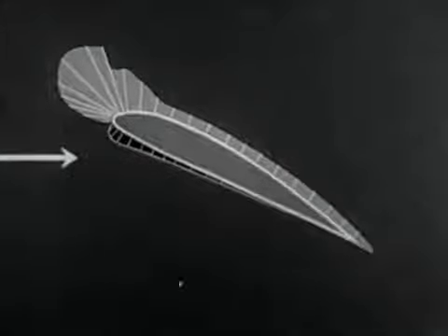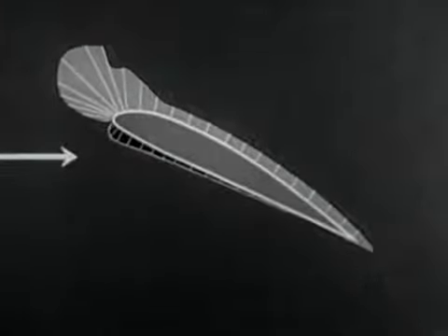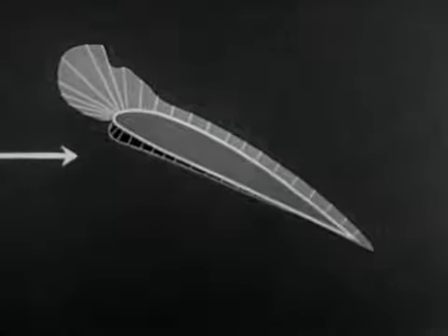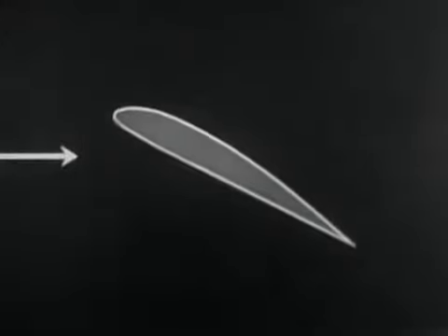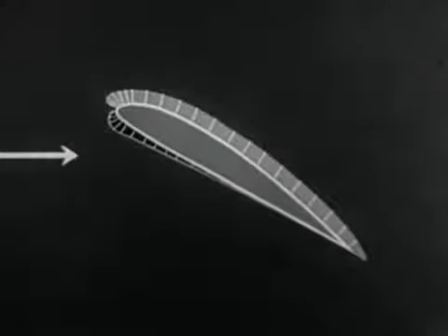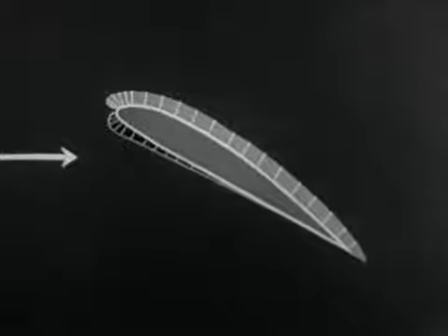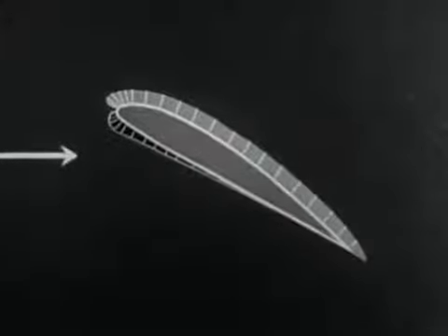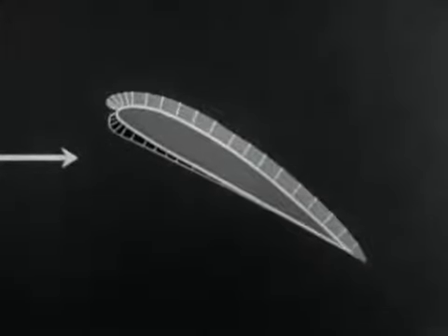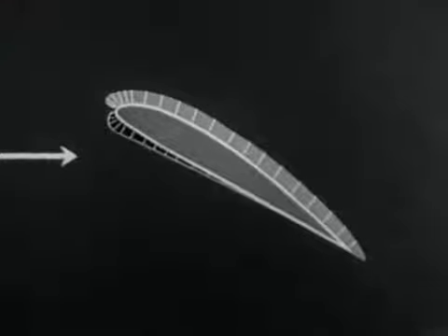Increased angle of attack brings no important change in positive pressure value or distribution, but the negative pressure area is tending to equalize in value over the entire upper surface of the wing. At this angle of attack, the forward protuberance disappears completely, and an area of nearly equal negative pressure blankets the entire upper surface of the wing. Positive pressure areas still show no important change.